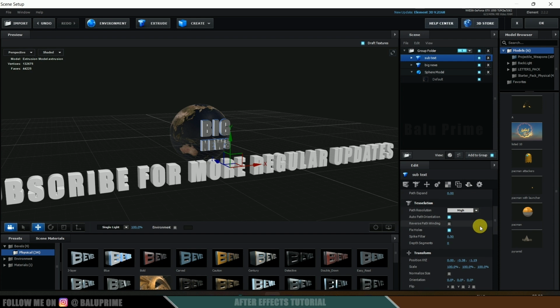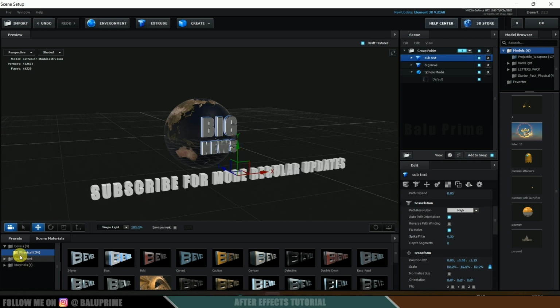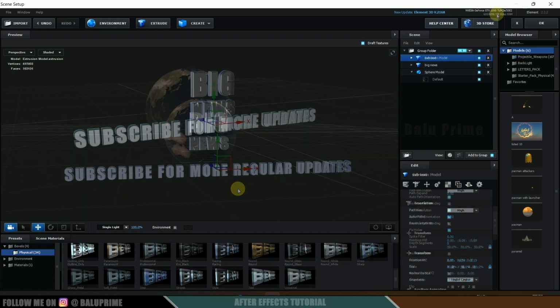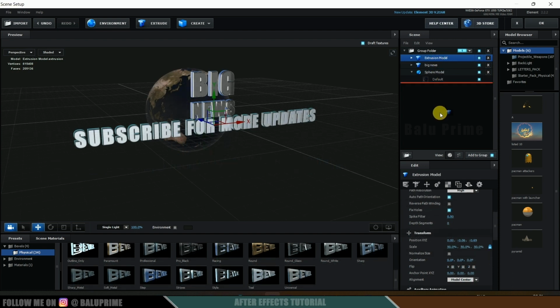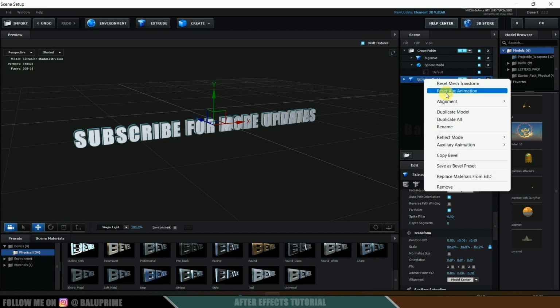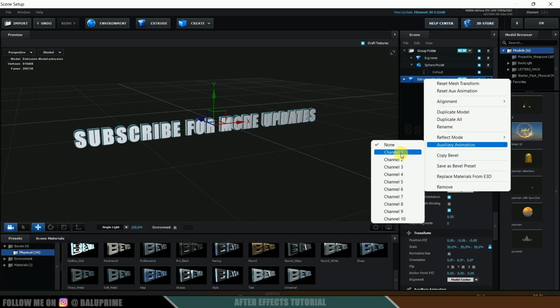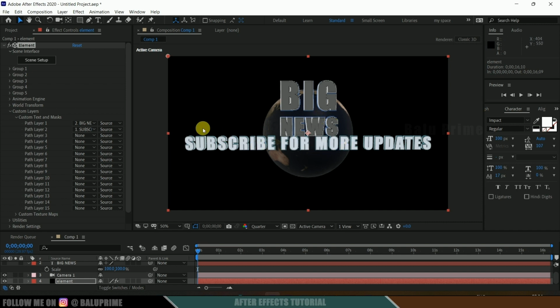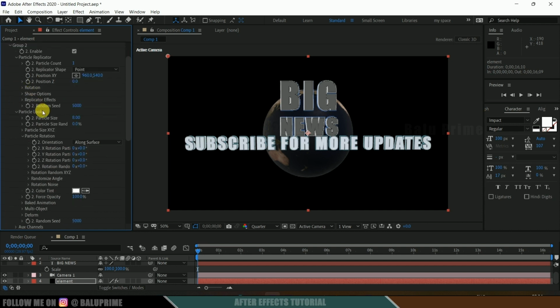So now let me reduce the scaling to 50. So I think this is fine, and let me apply physical material. So I will select this one, drag and drop. So let me drag it out from group 1 and make it as group 2. Now right click, aux animation, set it to channel 1. Now click on this OK. So we got our text here. So in order to make this wrap around earth, first let's come to this group 2. Since it is in group 2, scroll down.